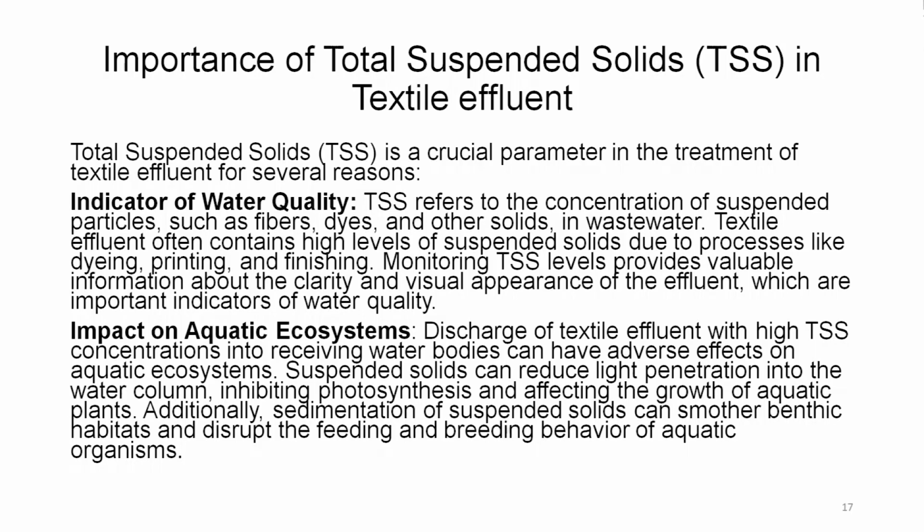Total suspended solids is a crucial parameter in the treatment of textile effluent for several reasons. Indicator of water quality: TSS, total suspended solids, refers to the concentration of suspended particles such as fibers, dyes and other solids in wastewater.